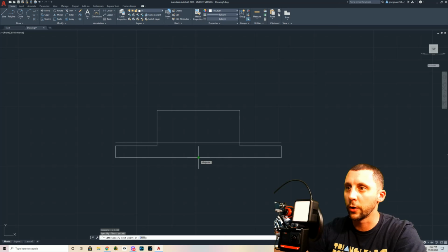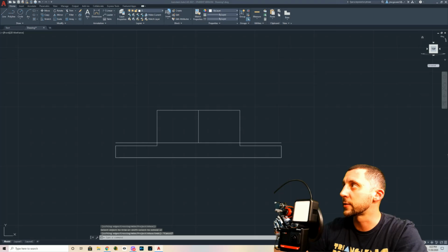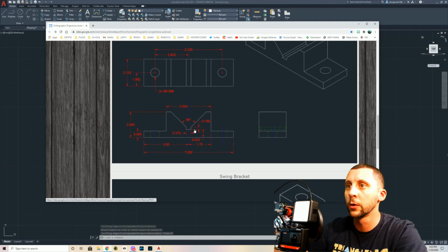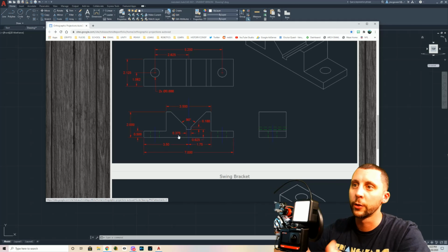Okay, so I'm going to draw this, and I'm going to go straight up to the other midpoint up there. I can also trim the bottom part. I don't need that anymore. You guys remember, as I said before, that the notch here is 3/8 of an inch wide. So I have to measure half of that going left and half of that going right. Half of 3/8. Anytime you try to get half of a fraction, you double the bottom number.